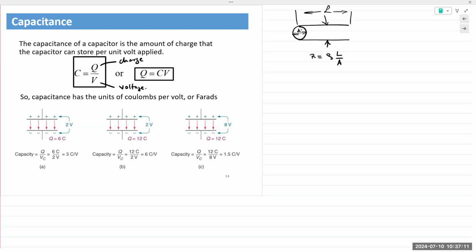And when electric current passes through those coils, they oppose the flow of that current. And because it opposes the flow of current, it gets hot. Now, if it was made out of very thin wire, it would just blow out. But it is designed to dissipate the heat as much as it can. It gets hot, and we can use it for ironing clothes.